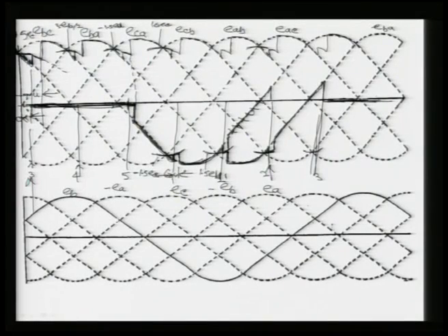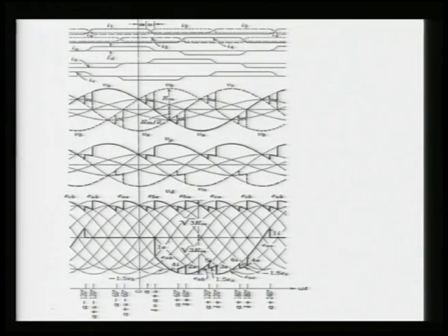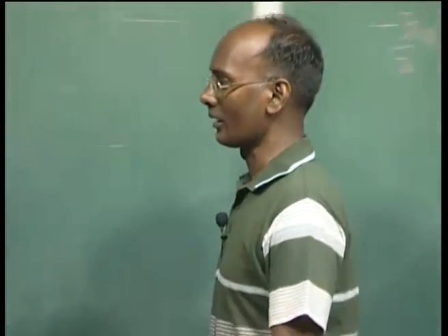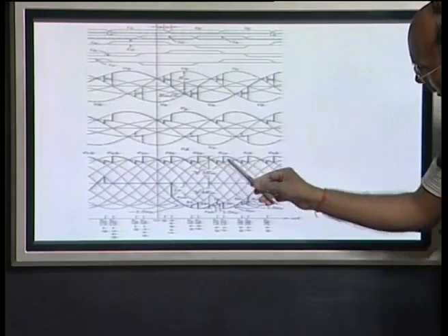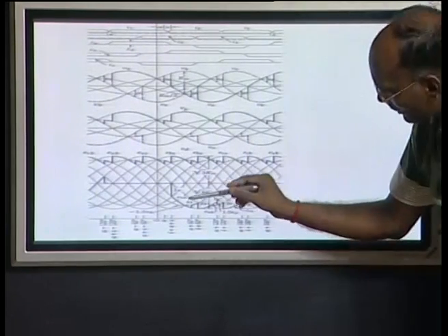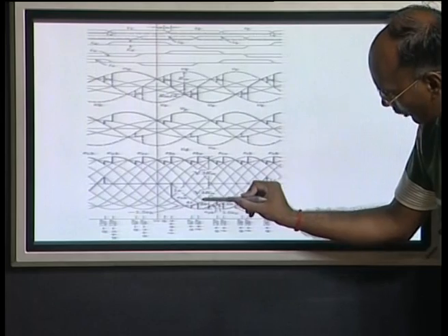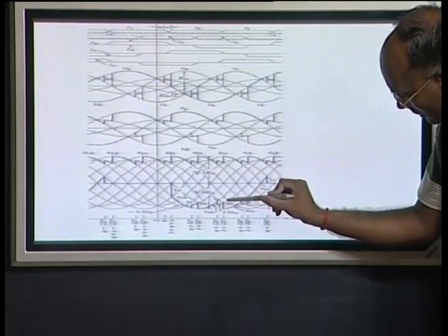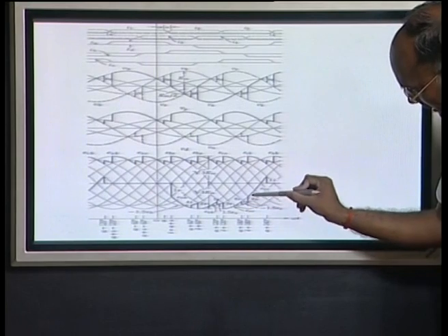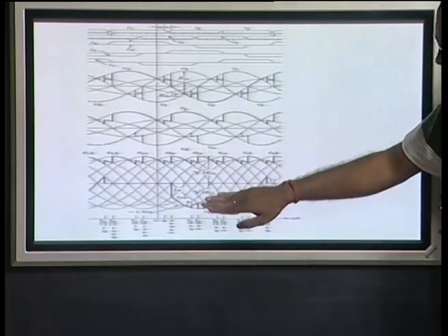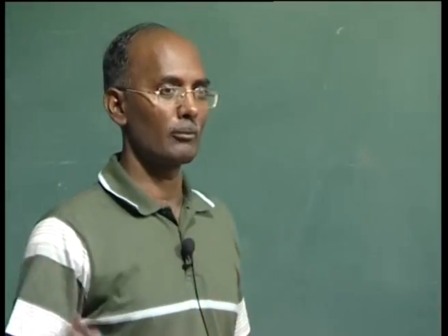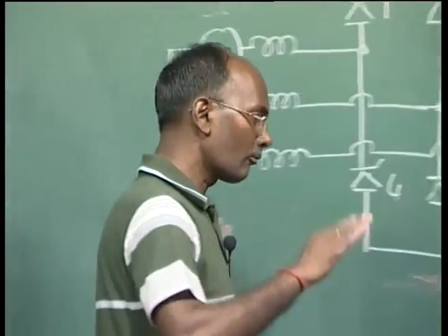Here it looks very dirty. Now, you can see the valve voltage here. This is the output voltage, and here again we draw the output voltage across this link. In the valve voltage, once the valve is conducting, you can see there is one dent. Then here is again the overlap, here again this, and then finally it comes to 0. It is similar to what we drew. For all the valves it will be the same shape, only shifted by 120 degrees. So, the pattern will be the same if it is symmetrical firing, and we have assumed that symmetrical gate pulses are given to the valves.